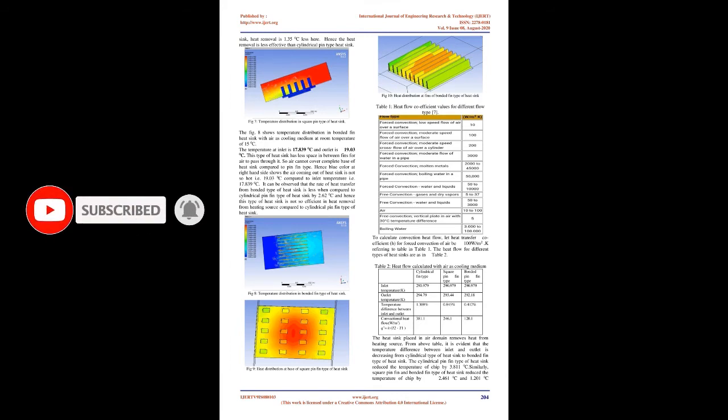As mentioned earlier, the atmospheric temperature is 15 C. The blue part represents cold air at temperature 17.8390 C entering the heatsink. The increase in temperature by 2.8390 C is due to the influence of the temperature of the heatsink, which is placed inside the air domain. The temperature of air increases due to convection, and hence heat is transferred from the heatsink to air, which is the cooling medium. The right-hand side has red color and indicates the air coming out is hot, i.e. 21.650 C, and hence heat is removed from both chip and heatsink. The temperature at inlet is 17.8390 C and outlet is 21.650 C. Hence the heat is removed effectively.